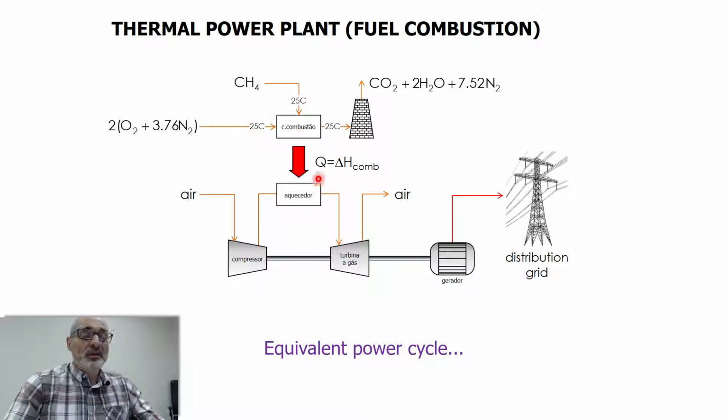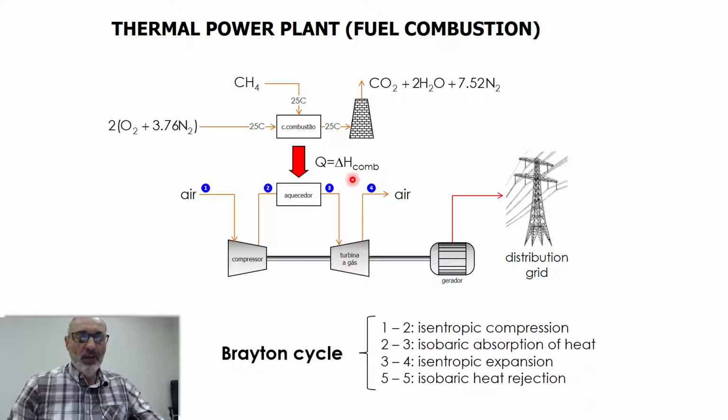So you can do this calculation, and you can assume that the heat supplied to this pure air cycle is exactly equal to the combustion heat measured in a calorimeter, for which we have charted data, as I showed you. We can do the calculations. I'm going to show you how.